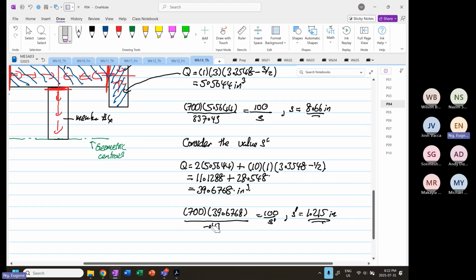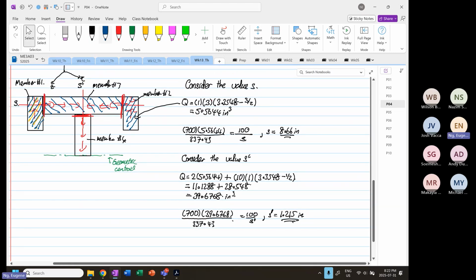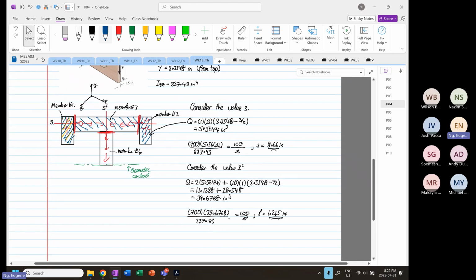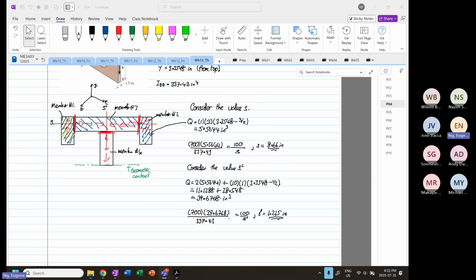Again, the most important thing is the shear flow must distribute through the entire member first. Then the fastener can transmit the load. That is the rules that I set. And with that, I hope it clarifies a lot of your doubt. Mike, you okay? Mike Yi, does this make sense?